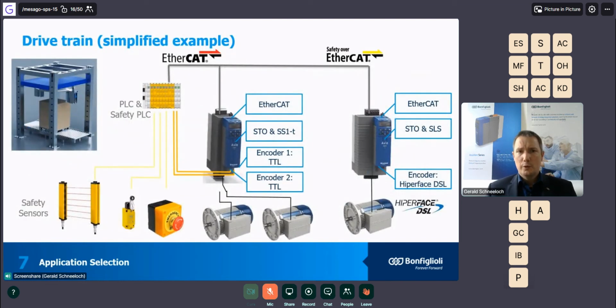To complete this description of our selection, I would just like to show on a schematic level how the proposed alternatively operated conveyors can be operated with one inverter while using encoder evaluation. So, through a contactor, operation could be easily changed, including the evaluation of the encoder, so that the inverter is used either as feed-in or as feed-out conveyor, which is especially interesting in applications with limited space.